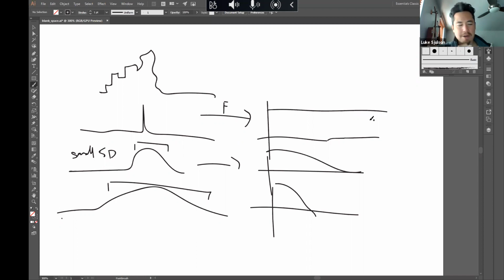The reason is that the way it works is that it takes your signal, cuts it in half, then cuts each half in half, and each of those halves in half all the way down. So even if you had 1025 data points, you would add zeros until it was 2048 long, and then FFT that. Newer commercial FFT implementations will actually look for multiples of powers of other small integers. So it might divide it into thirds, and then each third into halves. But that's this whole notion of the FFT as an algorithm, and why the length being a power of 2 is relevant.